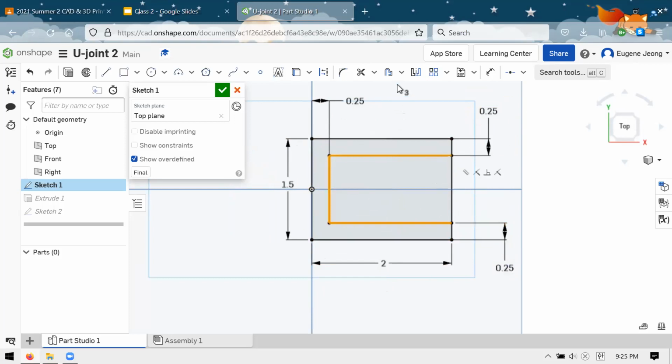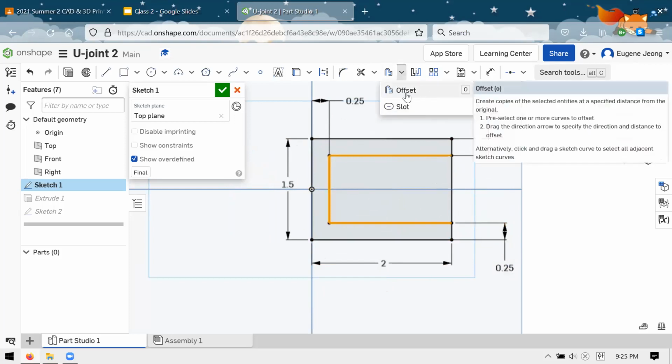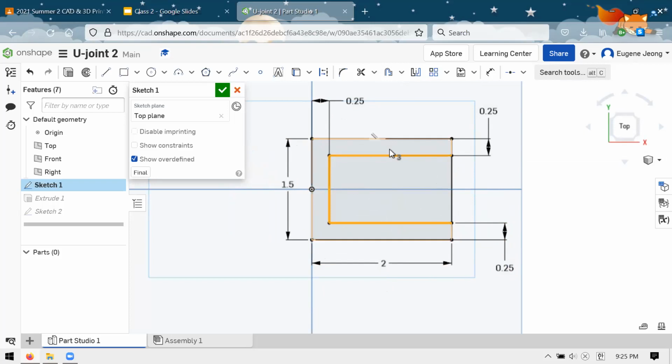There is actually a tool that you can use to do this automatically. It's called the offset tool, but for the sake of time, not explaining a new tool, I just drew 3 lines. If these aren't turning black for you for some reason, it's most likely because you're missing a vertical or horizontal constraint. Although if you are able to dimension it, those constraints probably exist already.